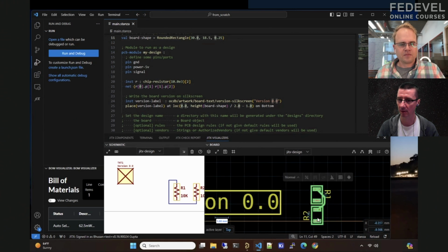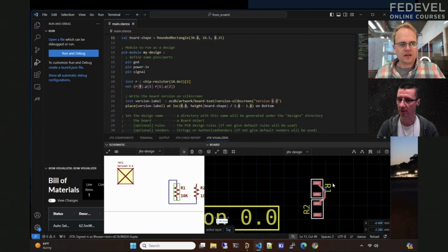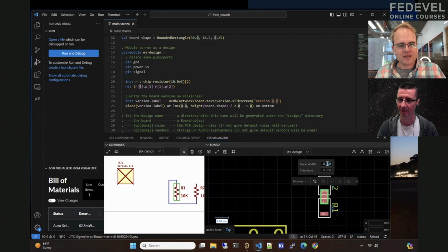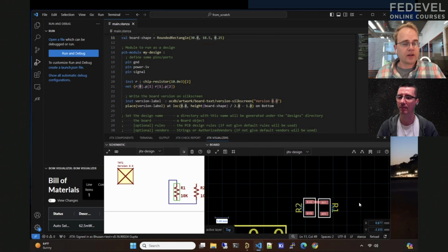How can you make it wider, for example? Yeah, you want a thicker one? Yeah. So you can do it in code, obviously, but you can also get in there and edit it. So thick trace. If it doesn't fit in the pad, it will make an adaptive shape. So I made that significantly larger than the pad. If I make that down to 0.2, it fits. So that unusual shape is really nice for power routing, as well as if you have sensitive RF structures, you can do very nicely tapered shapes pretty easily.